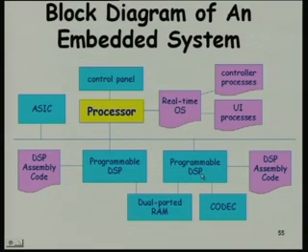And then we have digital signal processors and some specialized processors which possibly have their separate code, and there might be some application specific integrated circuits, and then we might have memory specifically for these DSP processors. Both of these are accessing this dual ported RAM, and we might have a codec for signal conversion and compression. So, this is the kind of system that we keep in mind as we proceed.